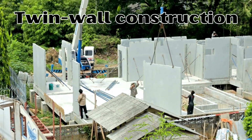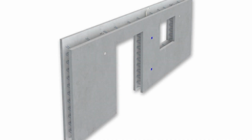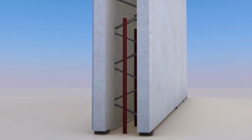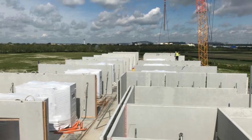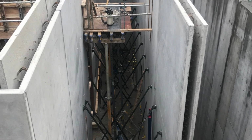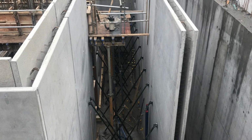2. Twin wall construction. Twin wall technology includes building a new wall out of two parallel prefabricated concrete panels. Construction workers assemble these panels first, then connect them with fresh concrete or steel lattice girders to offer structural integrity. Twin walls can be used to build a variety of structures, including houses, hotels, and schools.